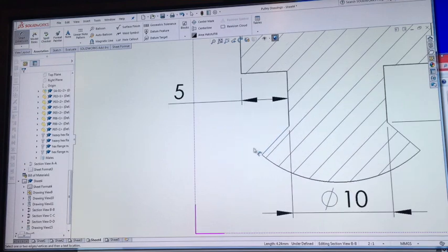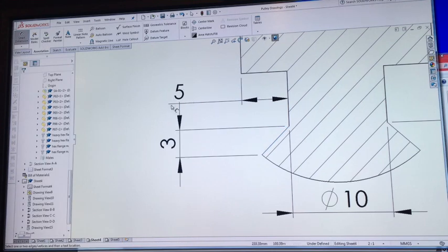So when you're doing dimensions like the one on the angle here, if we want to dimension this height, where you move your cursor, you'll get a different measurement, just like you would when you're sketching. So again, just move that one to the side, move that one up.